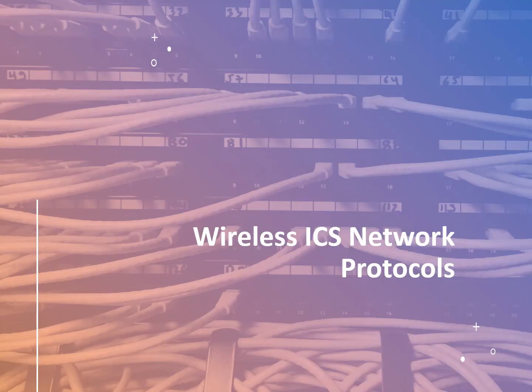The wireless variety of ICS protocols and standards includes WirelessHART, IEEE 802.11 Wi-Fi, Ethernet radio, IEEE 802.16 broadband, ISA 100.11a, and WIA-PA. WirelessHART, based on the IEEE 802.15.4 technology and released in 2008, has the largest install base.